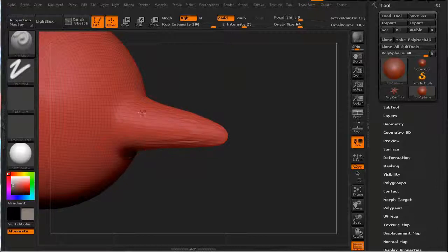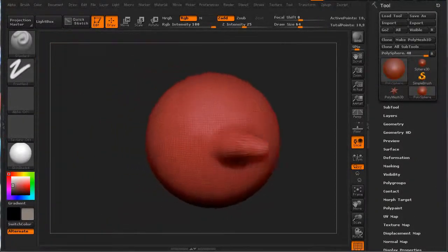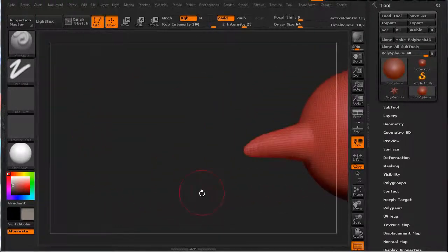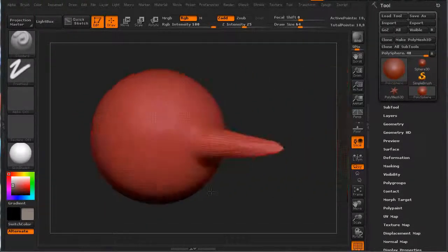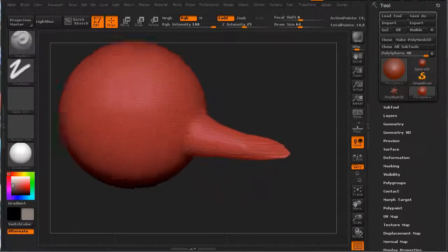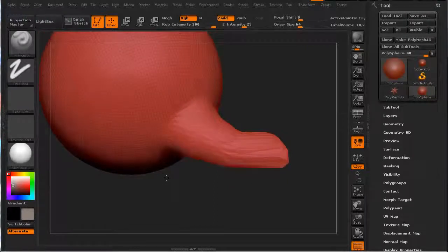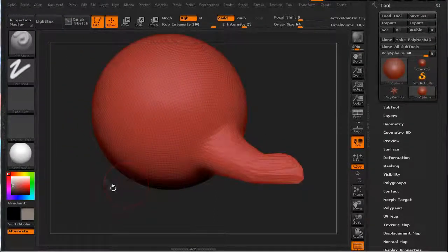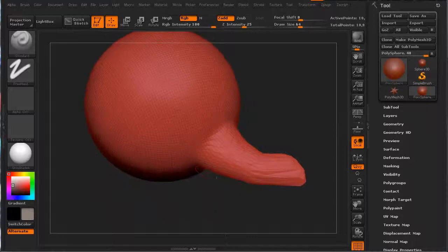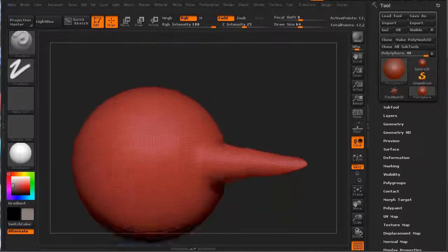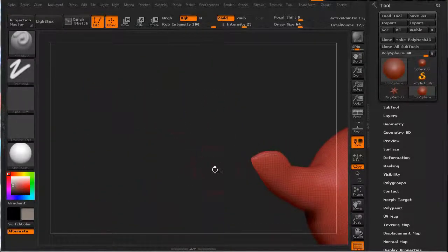See this? This is not good. Obviously, if you're going to sculpt with that, and we continue sculpting with it, and we can, it just stretches it farther and farther out, and it's not going to help us with what we want to be able to do. The beauty with Dynamesh is, let's say this is the start of something I wanted to keep. If you just hold down your Control key and draw a rectangle in the background, see how it redistributed the polygons? Now I no longer have any stretched polygons on that.